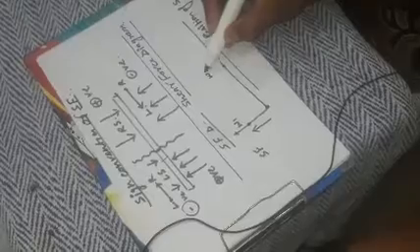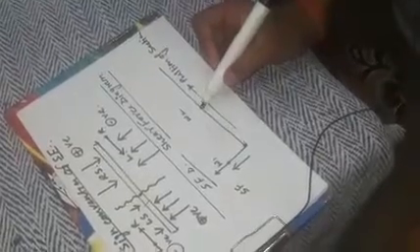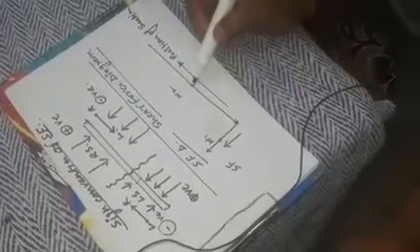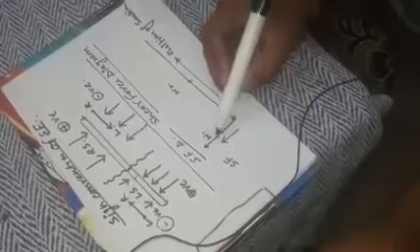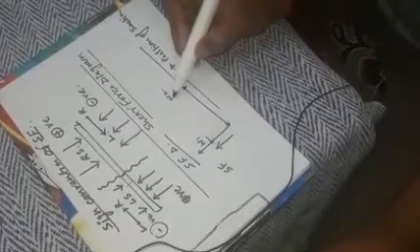For this point, the shear force value is here, of amount W1, and for this point it is W2, and the variation between these two loading points is, if the beam is subjected to a point load between these two points, then say it is subjected to a UDL between these points, then the graph will be an inclined line like this one.